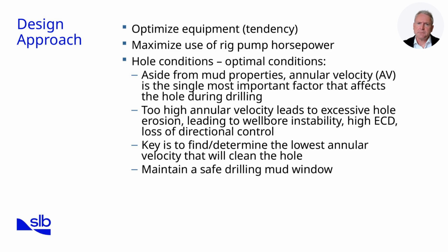In the design approach to achieving effective hole cleaning, the first point is to optimize equipment use. This involves maximizing the use of available rig pumps, nozzles, and drill string rotation to optimize fluid circulation. Even with limited horsepower, equipment settings can be adjusted to maximize efficiency without overloading the system.